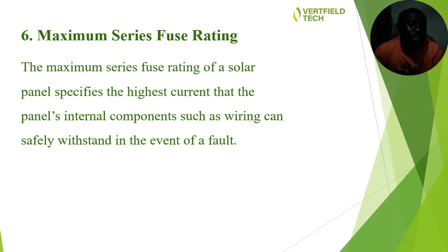This simply means that in terms of safety, if you have considered using fuses or fusing your solar panels, this technical parameter, maximum series fuse rating, tells you the actual size of fuses that will be used for each series fusing for your solar panel. Yes, you must be very smart about this. You must know what you are doing here, because for you to fuse your panels, it means that you already know what you are doing and what you want. So that is on the aspect of safety.